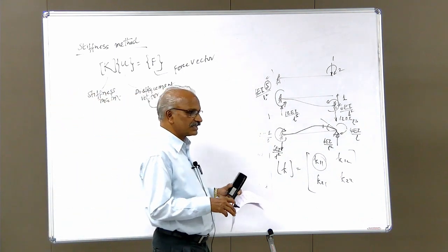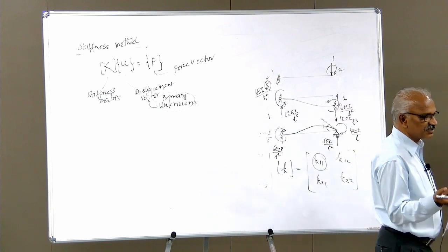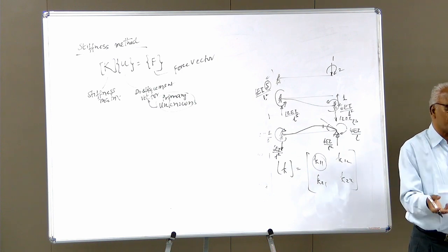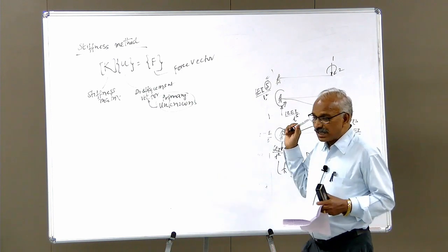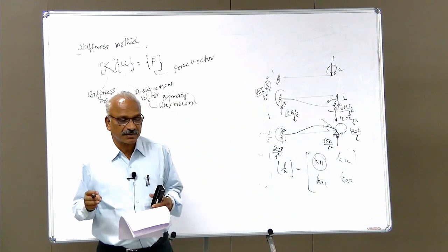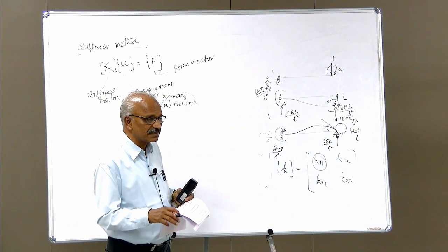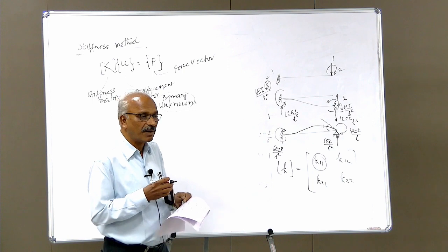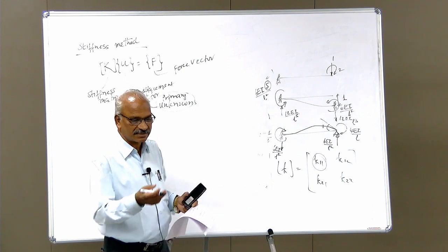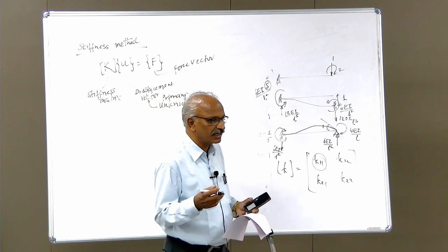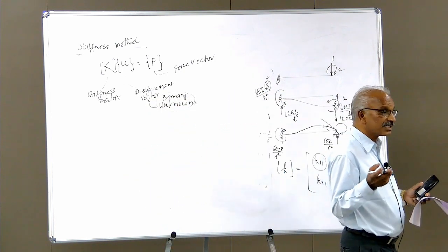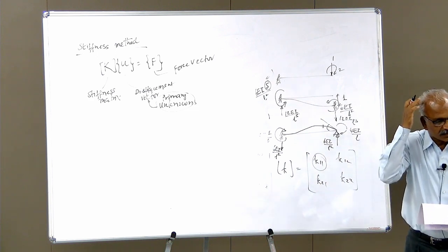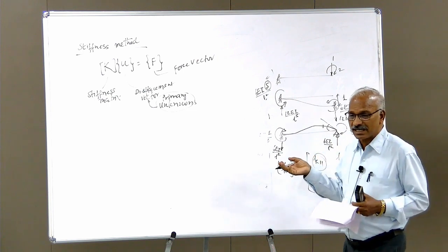Now here, kinematic indeterminacy. So for statically determinate structures, the size of the stiffness matrix will be equal to the number of coordinates as before. For statically indeterminate structures, here we are using kinematic indeterminacy. Therefore, the size of the stiffness matrix will be equal to the degree of kinematic indeterminacy, number of possible joint displacements, as we have followed in the slope deflection method, theta A, theta B, theta C, delta. What are the possible joint displacements? So that will decide the kinematic indeterminacy, stiffness matrix in the case of statically indeterminate structures.